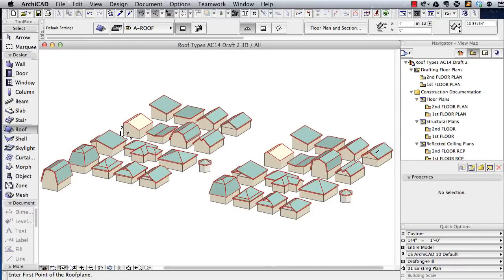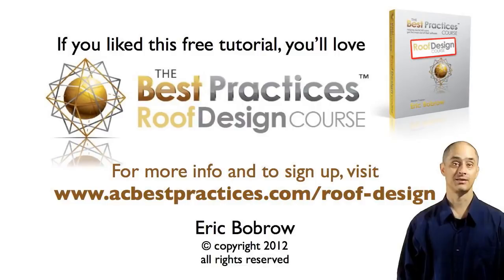And there was one other wrinkle back here, was that one with the box gable, where we had to change the setting for the trimming body for the roof in order to accommodate that, to make sure that the extra piece that was sitting outside the main walls, the main pivot lines, was being trimmed properly. So I think this concludes my study of the main differences in basic operations on roofs in ArchiCAD 15 and 16, and still going through all of the different roof types that were covered in the earlier lesson.